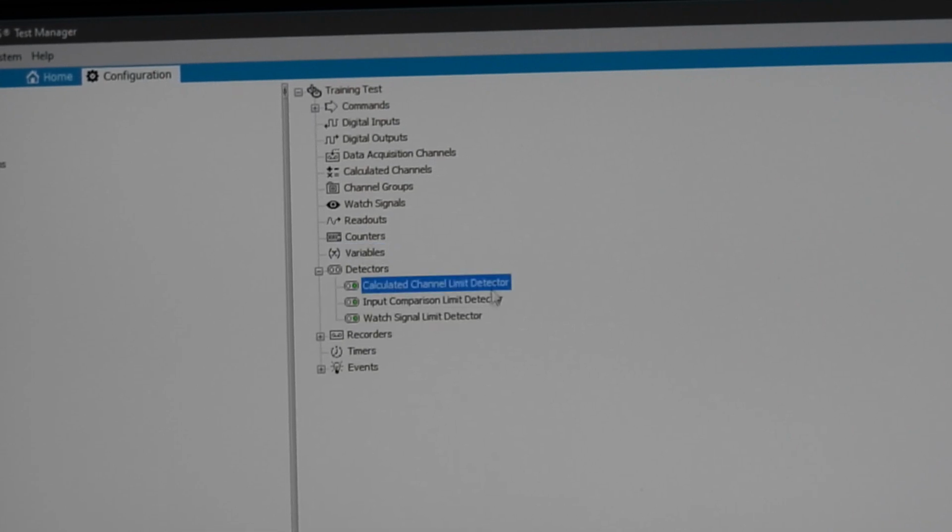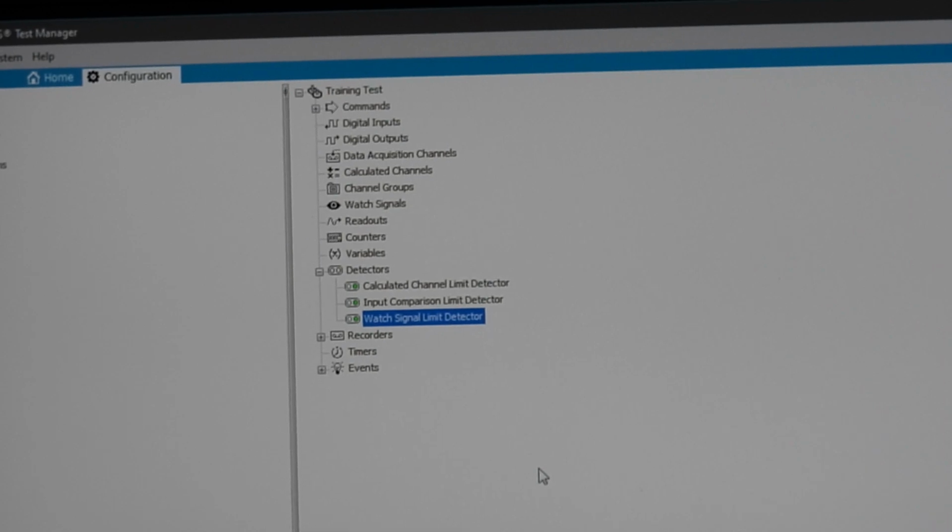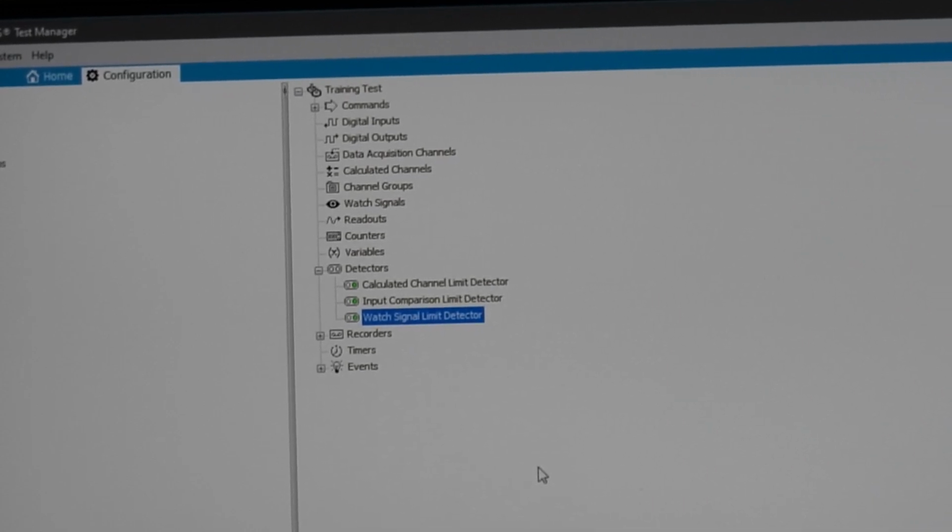Detectors, I don't know if the detectors are going to mean a lot. Typically, just like on the flex test side, you're doing control, your limit detectors are there to protect things. Here we're not doing controls, so you can have limit detectors set, but if you start to have things trip, you would want to be very cautious about what actions you have set from those limit detectors, because it may disable that acquisition. You're halfway through your test and things have now stopped on one side that you were depending on. We would never use that.